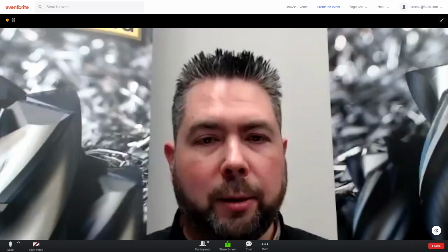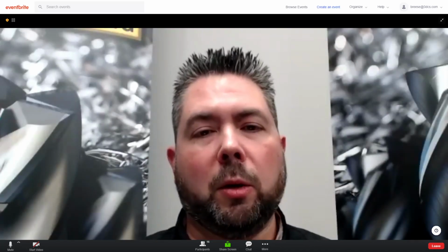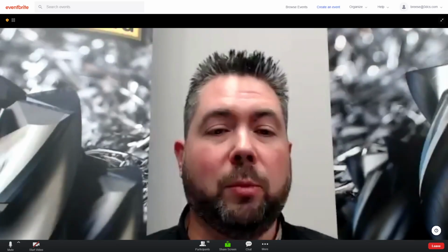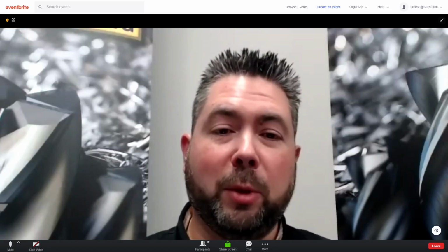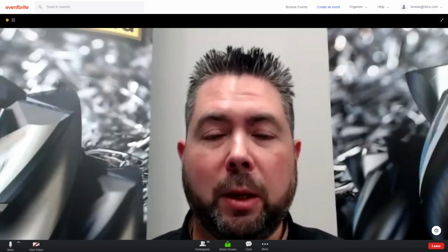And again, like I said, always remember that one person's finishing cut is another person's roughing cut. It might be only 1 millimeter taken off the side, but if it's got a 0.5 millimeter corner in it, somebody's using a really tiny end mill.